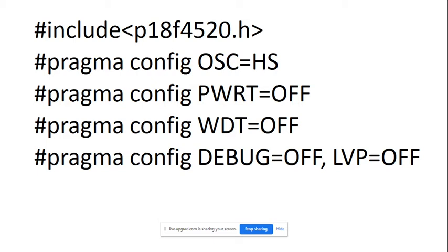Any time our system hangs, there are two ways, either you reset manually or automatically. Manually, it is not possible every time to go to that particular location and reset the system, because our system runs 24 hours. In that case we prefer automatic reset, meaning we take the help of the watchdog timer.